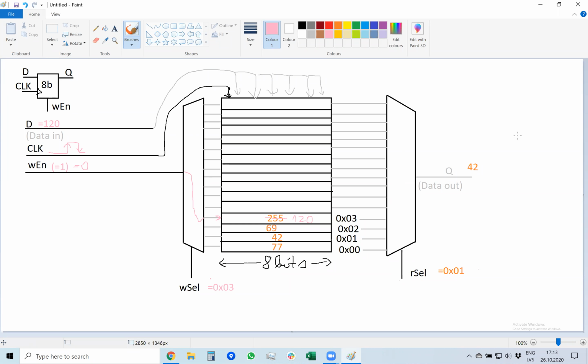Okay, so on one side we have read. We read information by selecting the cell and outputting it to data out. And we write by putting data in, write enable, select the memory location to write, and then we do clock rising edge, and it stores the value. And then on falling edge, we, for example, switch off all the signals. Okay.